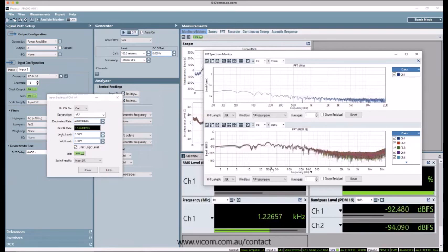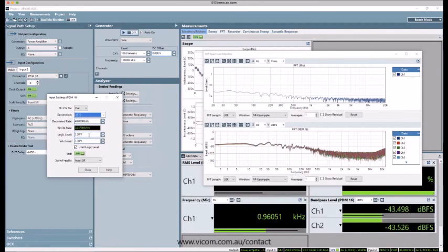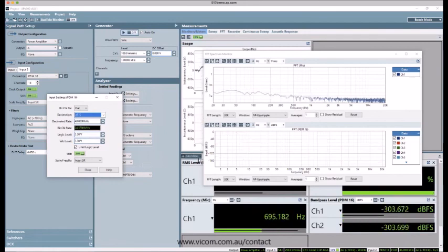So if I decimate it at a lower rate, I will see a wider output signal. If I decimate this signal at 32x or 1/32, now in theory my signal output is coming in higher than 48K. And if I decimate it at a higher rate, let's go crazy, I get almost no signal. Let's not go too crazy.